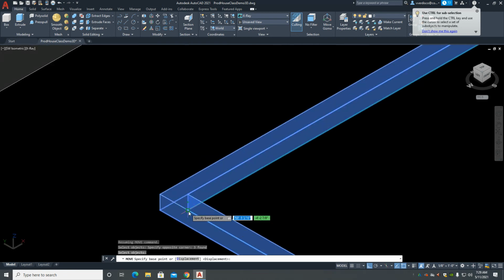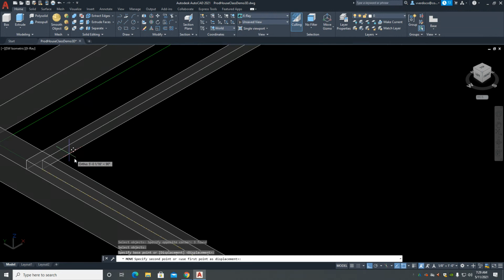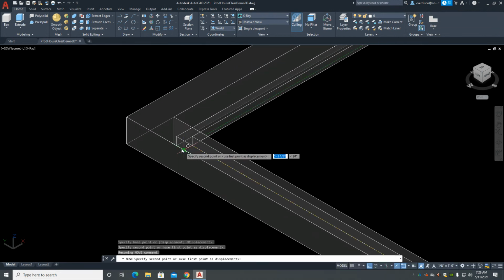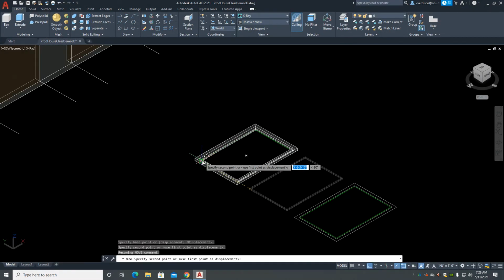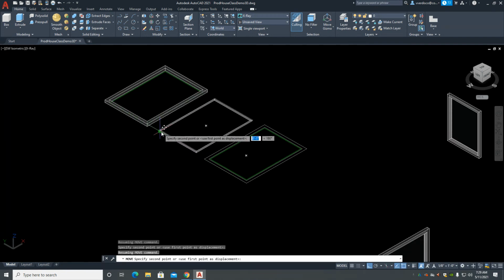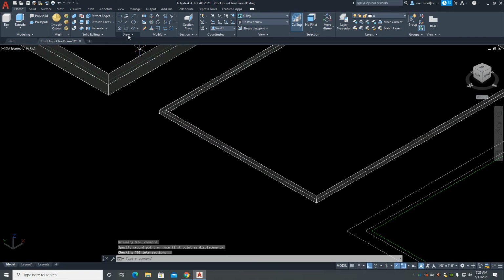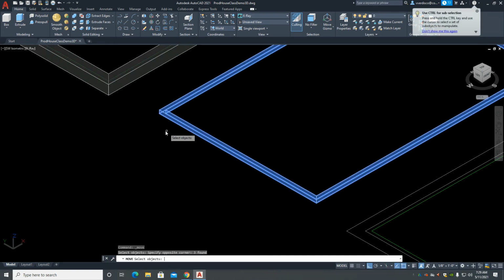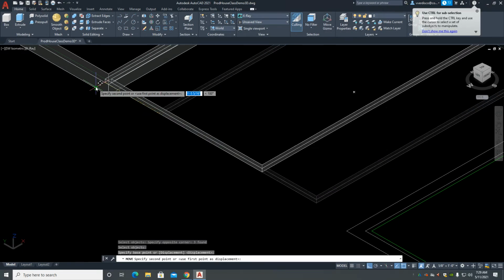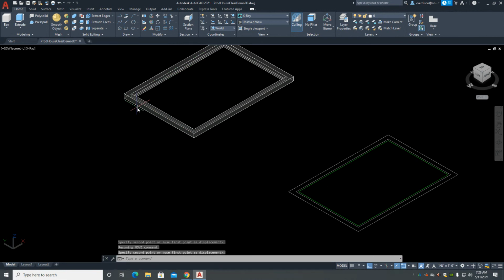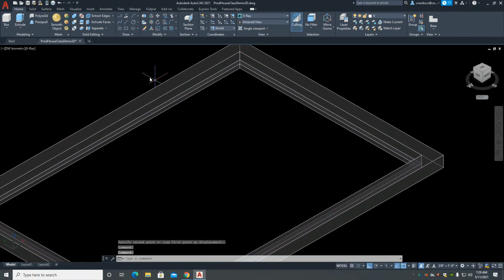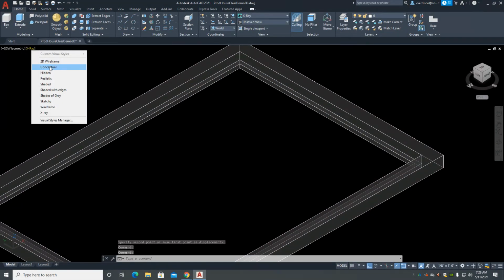Select it like this, grab it from the corner, the inner corner, bring it over here and find the inner corner here to link this to. That's not right. We got to go back. Grabbed it by the wrong part. We need to grab this one by the outer bottom corner, and now we need to find the inner bottom corner right there. All right, so now let's go back to conceptual.